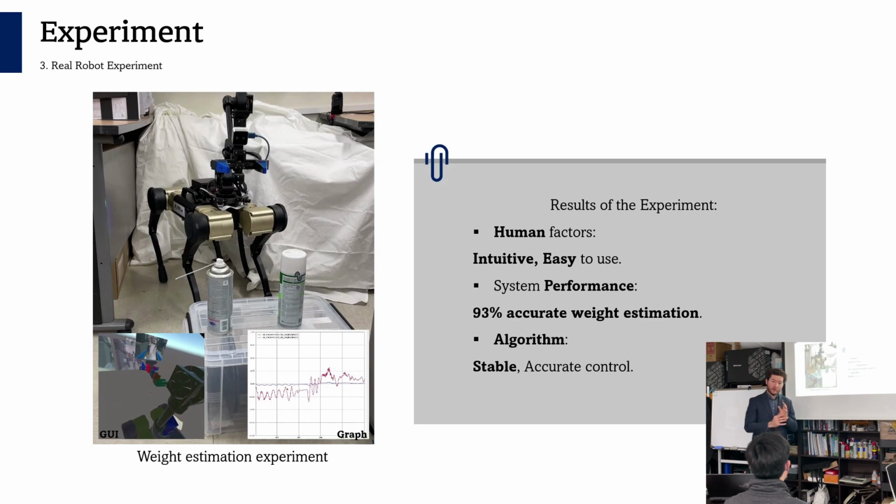the robot was not stable at all when I put it in. It is stable in its narrow task space, but when the robot is in a dynamic state and stretching its hand, it becomes very unstable. Yes, because the servo motor at the root might have a high torque necessity, the performance may be degraded. Also there may be structural vibration happening. And the coupling effect is very strong as well because there is a pitch joint, three of them in a row, all together.